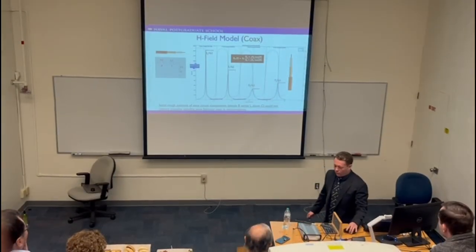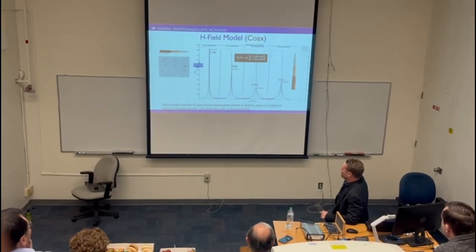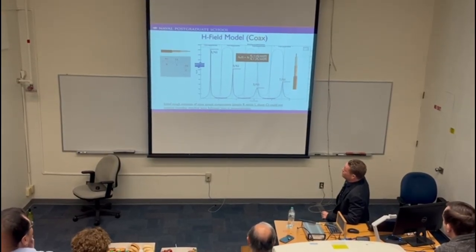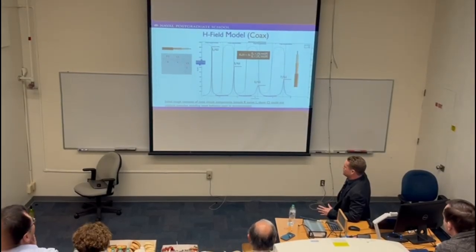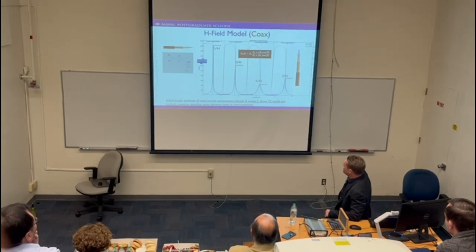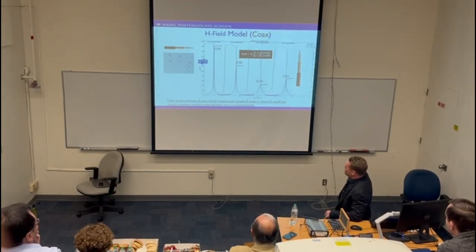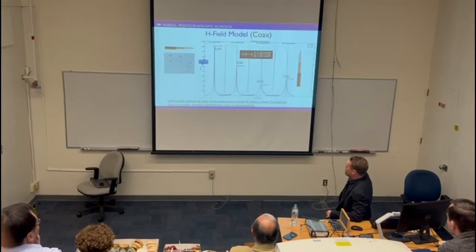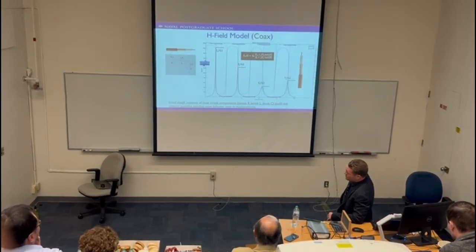Now, pretty straightforward was extremely far from straightforward. So the coax, I started off with something very straightforward, just a basic RLC type model, just a little second order RLC type circuit. Well, that definitely does not have the complexity needed to show some of the behavior that I was seeing in some of the measurements, such as standing waves here. You need to get into transmission line theory.